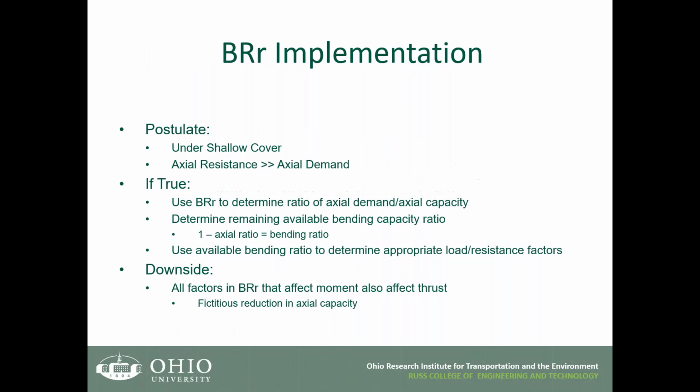So within BRR, the idea was, is there a way that we can utilize what's available in BRR right now to get a load rating? And so the way that we went about it was we wanted to look at whether there is a way to increase the soil cover to get BRR to run, but utilize a change in the density of the backfill material or the load distribution in order to, so to speak, trick the program to give us a result that's equivalent to what's actually in the field.